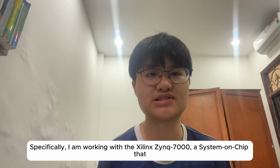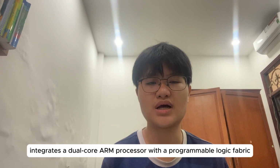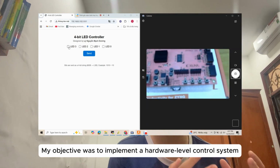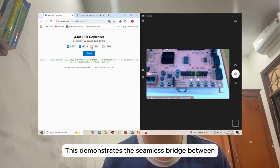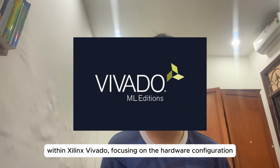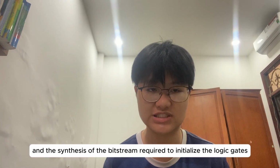Specifically, I'm working with the Xilinx Zynq 7000, a system-on-chip that integrates a dual-core ARM processor with a programmable logic fabric. My objective was to implement a hardware-level control system for the board's onboard peripherals, managed through a high-level web interface. This demonstrates the seamless bridge between software-defined commands and hardware-defined execution. In the following walkthrough, I will document the implementation within Xilinx Vivado, focusing on the hardware configuration and the synthesis of the bitstream required to initialize the logic gates.